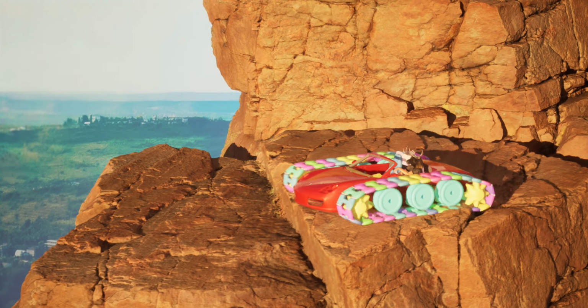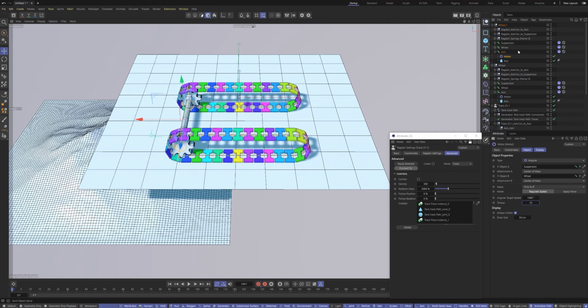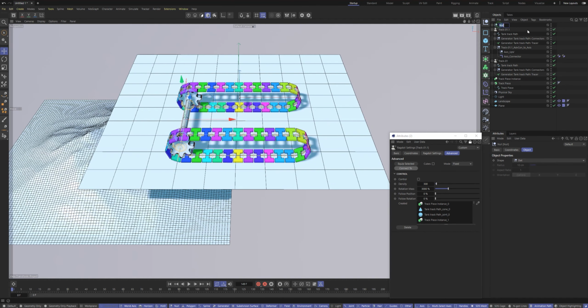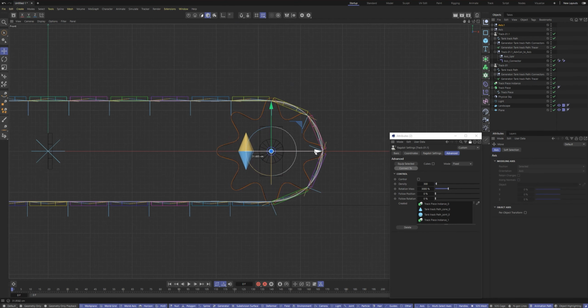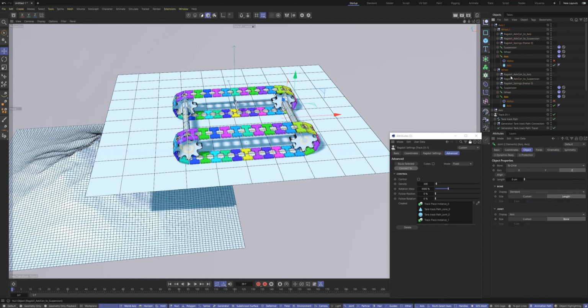To make your tank like this one, just add the back wheels and regular rollers between them. And of course don't forget to add the main tank body and fix all parts to each other. Play with the suspension spring stiffness, mass of different parts of the tank and the motor speed to achieve the desired result.